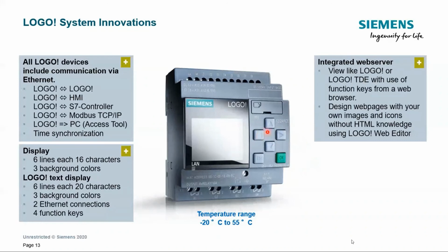So these cursor keys or the function keys of the text display can also be operated remotely from this web server when you are sitting on a web client, of course. Now, in addition to that, it allows you to design your own web pages with your own graphics and icons using the LOGO! Web Editor, free software that we have, and this does not require any HTML knowledge at all.